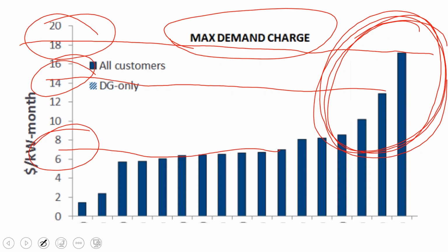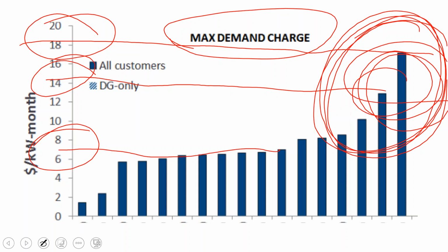But even when your cost of electricity might be 10 or 11 cents a kilowatt hour, a commercial bill in that same area might be 3 cents a kilowatt hour for the energy, and then up in this $14 to $20 a kilowatt charge for demand. And usually where these higher demand charges occur, if outside of high-priced electricity markets, is in rural areas, because to push all the power that a manufacturer needs to run their instantaneous manufacturing process, the utility has to supply that power, and so the more demand they need is how they bill it out.